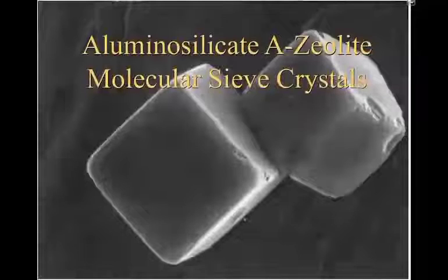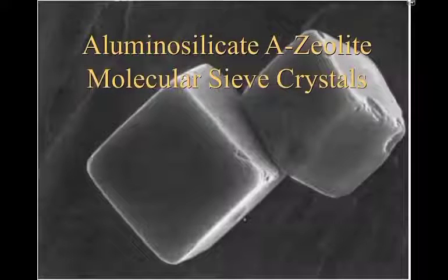Don't go into a lot of detail. Of course, you need a very porous material. This is a picture of an aluminum silicate A-type zeolite, certain structure. The crystals you're looking at might be 2 to 5 microns on a face, and within that structure you will have apertures or pore openings on the order of 5 angstroms or so in this structure.